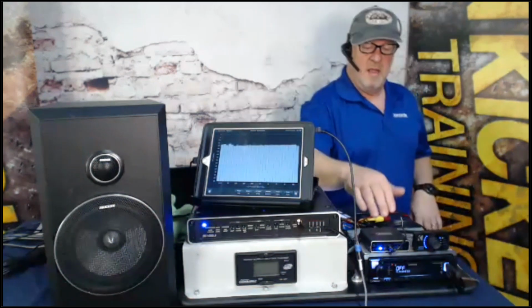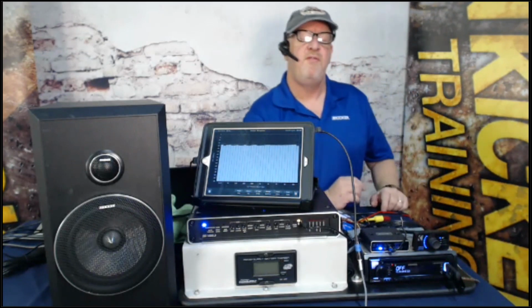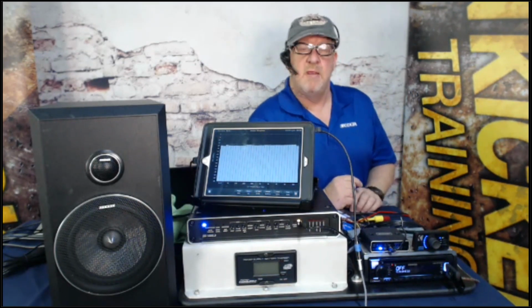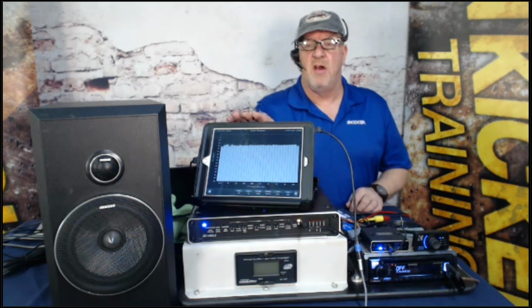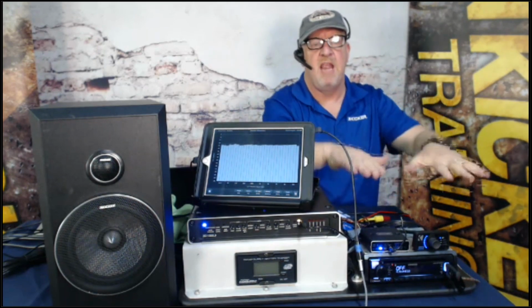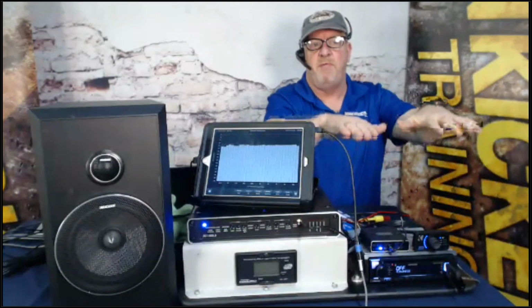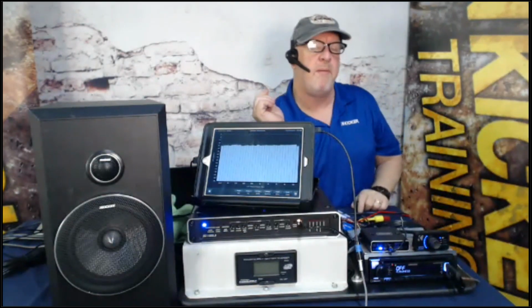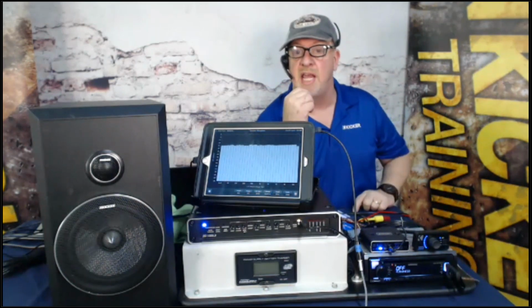The bass roll-off. And Aaron just mentioned bass roll-off. As we were talking about when playing the pink noise through the head unit, if you turn the volume up and down, if you remember when we did it at the beginning of the presentation, that signal on the RTA actually moved flat. But if as you turn it up, the bass stops and everything keeps going, you have auto bass roll-off, which is common in a lot of factory radios that do not have subwoofers.